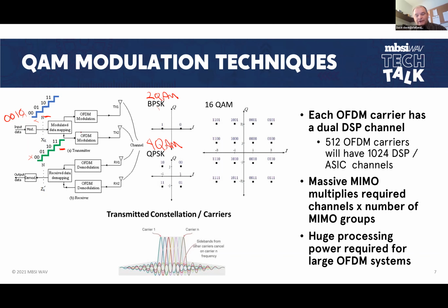these 2 streams are 90 degrees apart from each other, and the sum of these ends up being one of the points of the constellation. So this 4-step modulation gets modulated into 16 QAM. So I have a 4x4 matrix here. There's my 4x4 matrix, and so I have 16 discrete phase and amplitude points, I guess, that are created. I don't know what else to call them, but we'll call them points here since they're on here.